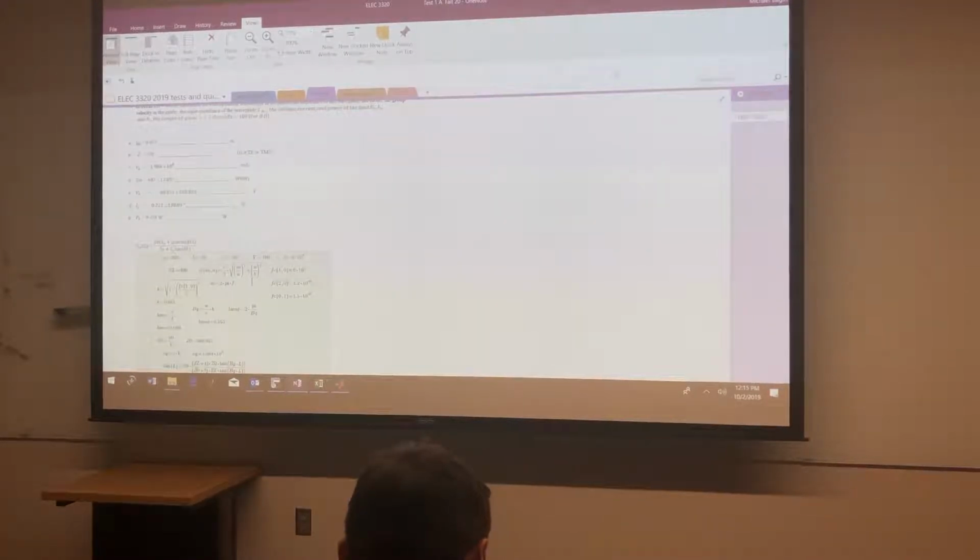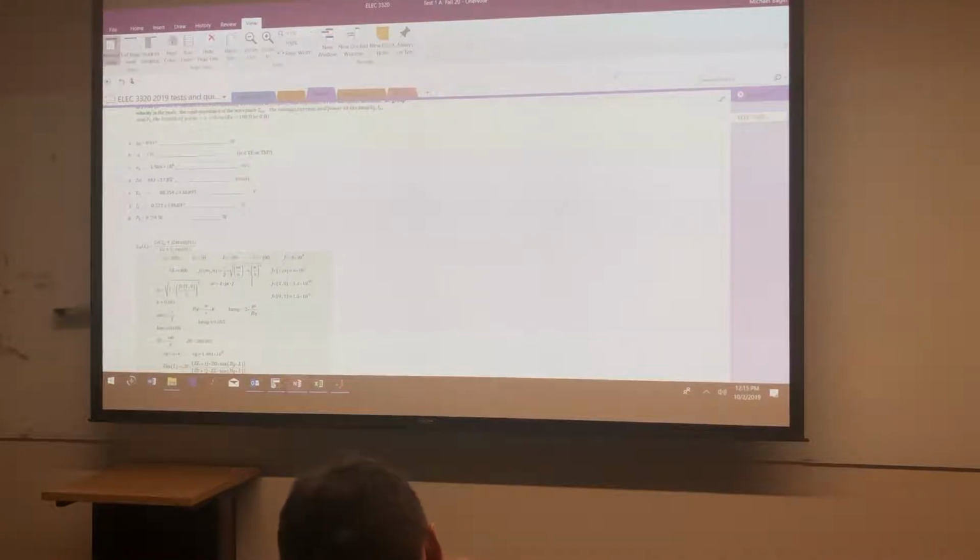Well, it's operating at 8. 8 is above 6, so it will operate in the 1 ohm mode. The next one above that is where? 12, right? We're not above 12, so it will never get that mode. It'll never be a 2 ohm mode. It'll just be the 1 ohm mode. Everybody follow me on this, class? I mean, most people got that part.